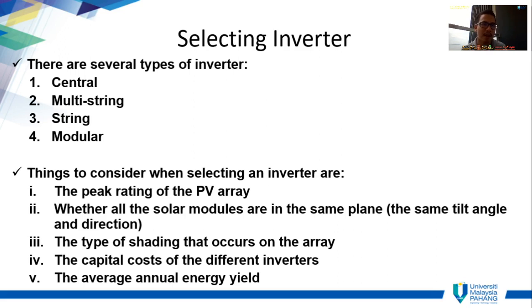But if it covers more than half of the surface of the PV module, even a single module, even at the edge side, it's very critical for you to avoid it.